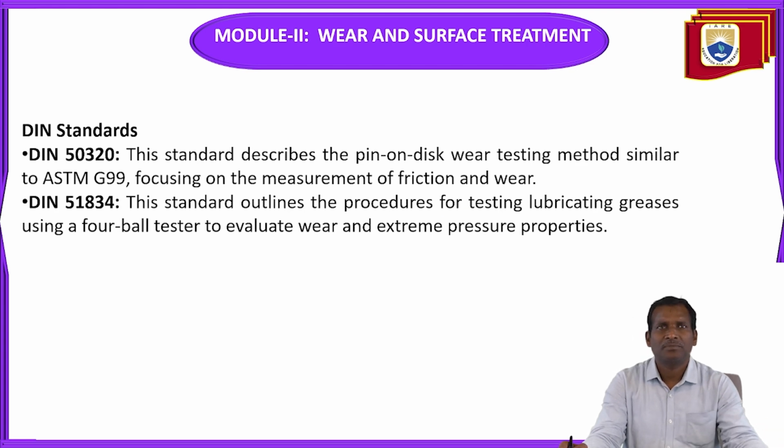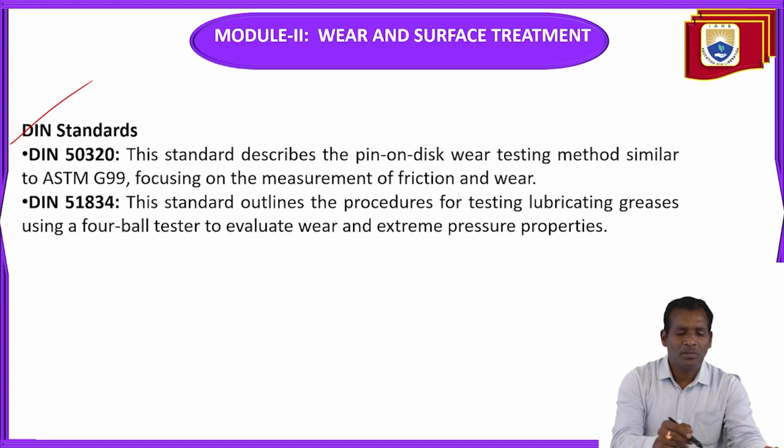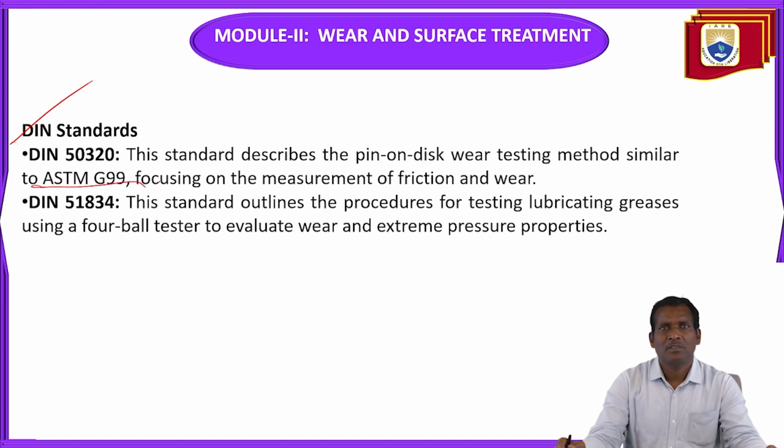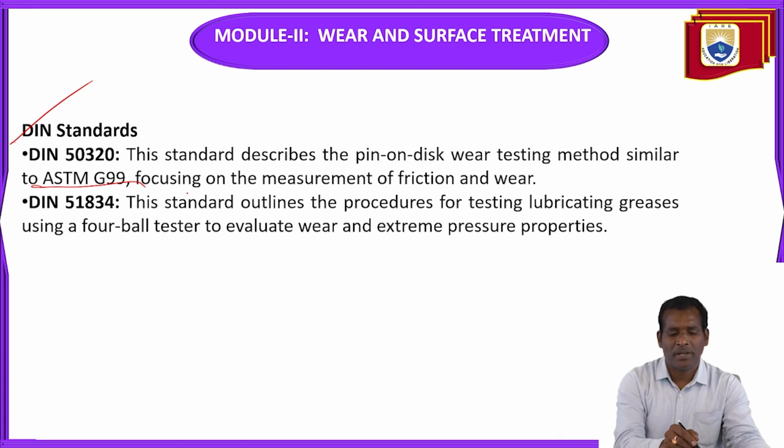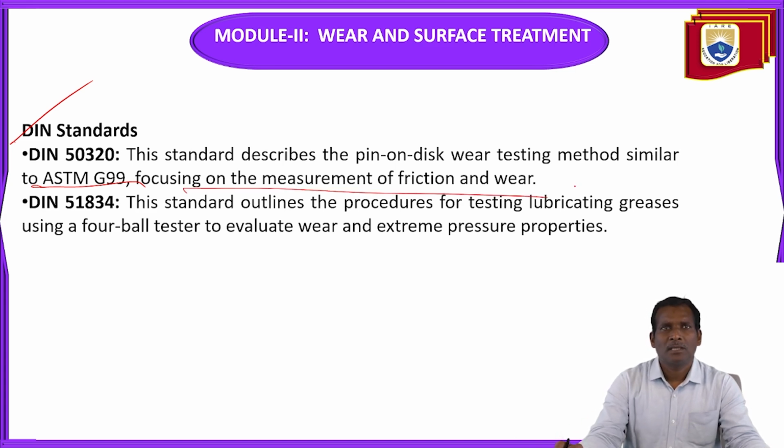Next, DIN standards. DIN 50320 describes the pin-on-disc wear testing method, similar to ASTM G99, focusing on the measurement of friction and wear. DIN 51834 outlines the procedures for testing lubricating greases using a 4-ball tester to evaluate wear and extreme pressure properties.